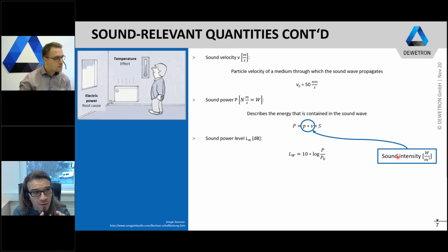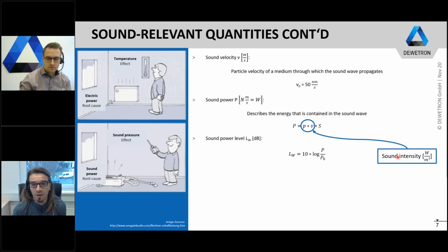It's just depending on the radiator itself, the power of the radiator, but not on any environmental conditions. But the temperature instead is depending very much on the environmental conditions. And in general, you can say that the further you are away from the radiator, the lower the temperature you sense is. And that's exactly the same behavior as the difference between sound power and sound pressure.